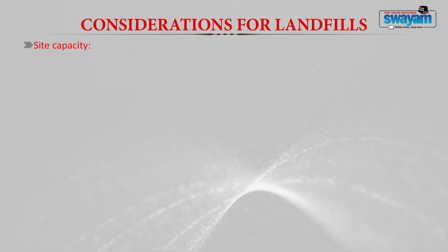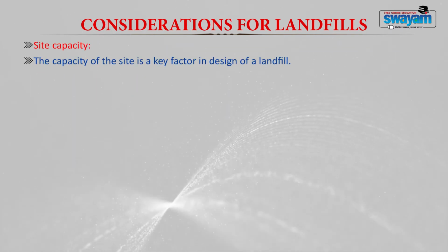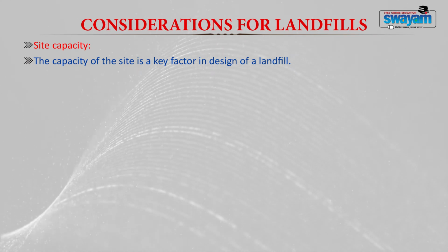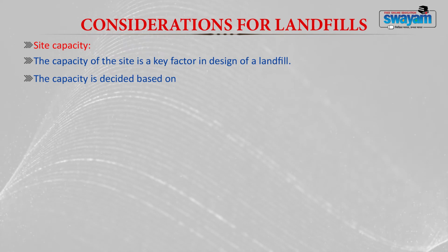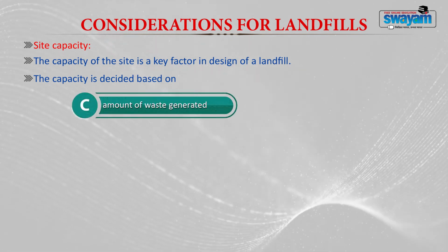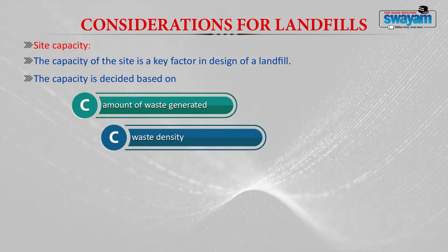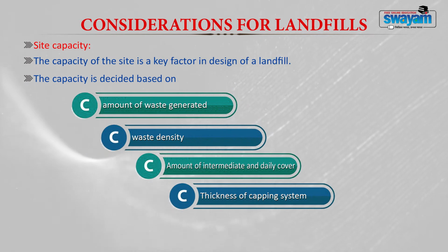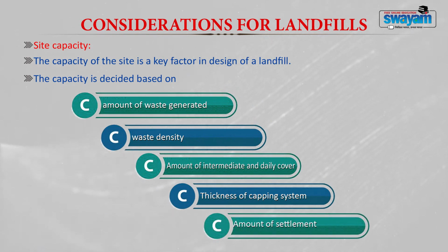Now, site capacity, as I told you, the capacity of the site is one of the important key factors which determines the design of a landfill. The capacity of the landfill is decided based on: 1. The amount of waste generated, 2. Waste density, 3. Amount of intermediate and daily cover, 4. Thickness of the capping system, and 5. The amount of settlement that occurs in the landfill.